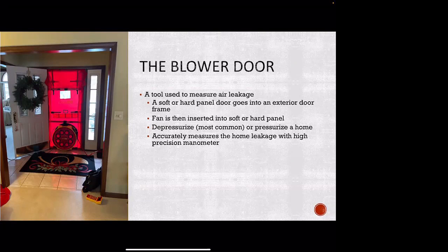That fan then can do two things. We can depressurize a house, which is the most common, or we can pressurize a home. Now, why would we depressurize? Why would we pressurize? Well, depressurization, especially in the colder months or the warmer months, will actually make those air leaks more visible. However, we may have to pressurize a home.